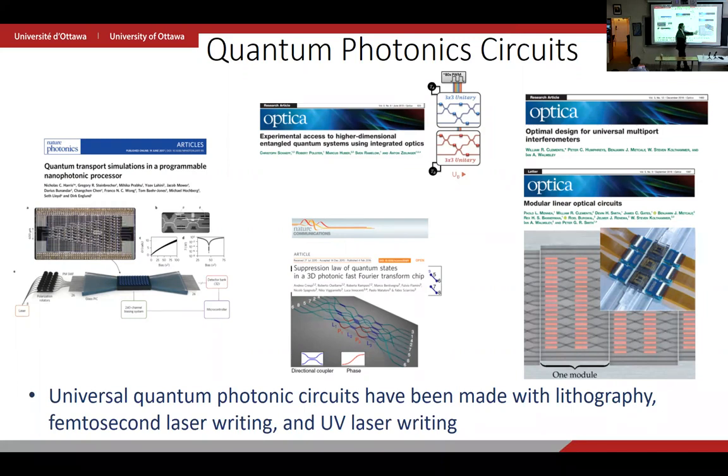They've made them modular. Remember, they're replacing the variable transmittivity beam splitter by Mach-Zehnders. So this is our Mach-Zehnder right here, and that's now a fixed 50-50 beam splitter. And now these are the phase shifters. So now you can just think of this as layers. You can make a chip with just a single layer or two layers, and then bring another chip in, make it exactly the same way, and attach them together. So you can make a circuit that is as long as you want. It kind of simplifies some of the fabrication.